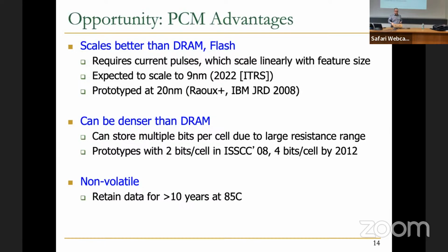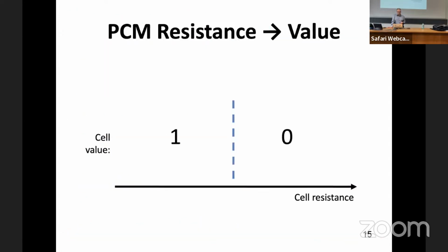Yeah, and PCM is also non-volatile. It can retain data for more than 10 years at 85 degrees Celsius, which is quite good. So without refreshing the PCM, the retention time is greater than 10 years. No refresh needed, low idle power.